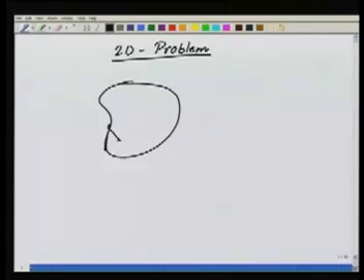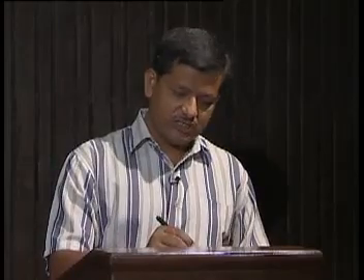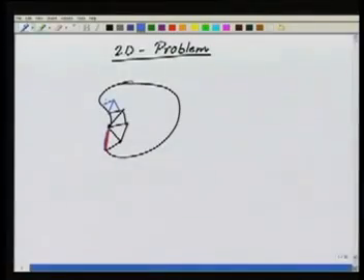Okay. For example, I mesh my domain with triangles. This is my domain. I know that these triangles with straight edges will only approximate this boundary curve. Okay. So I have to ensure that this approximation of the boundary curve is decent. That is, I have a sufficiently refined mesh, that is a sufficiently large number of small triangles at the boundary so that these curves are taken care of.